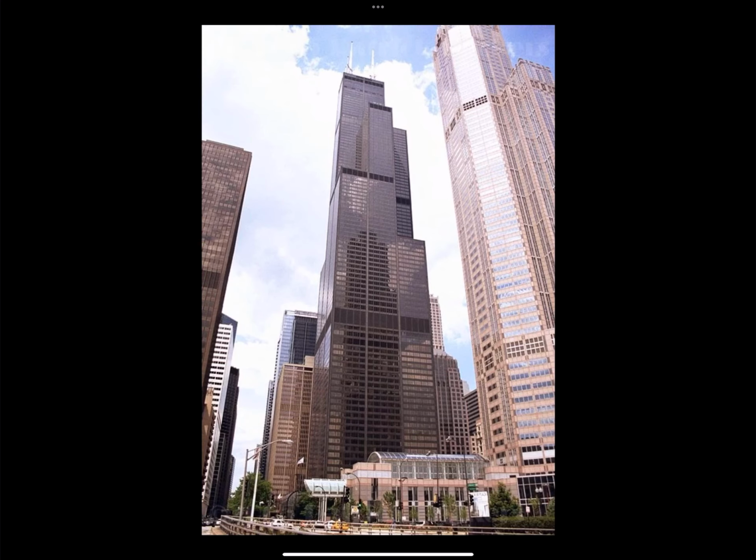So if we look at the Sears Tower again, we will see how these elements were prefabricated. And so to achieve 110 stories in height, the structural concept of this building is called bundled tubes. So there are 9 tubes that are bundled together to make a square. And each one of those is structurally rigid.